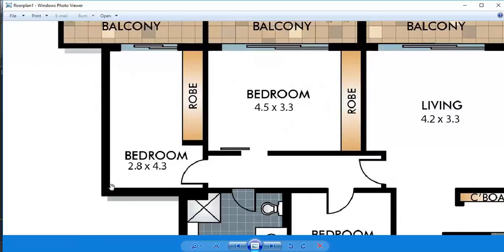So I think the robe is a problem. I would just take that out. But then the door, I don't think it really gives you that much extra by having it open out. And it's a terrible thing from a design point of view. It just makes it an unpleasant space. If you have an outward opening bedroom door, I think it's something you should never have in an architect designed interior. So it should be, as a minimum, having those elements that give it extra quality, like doors that open in the right direction.